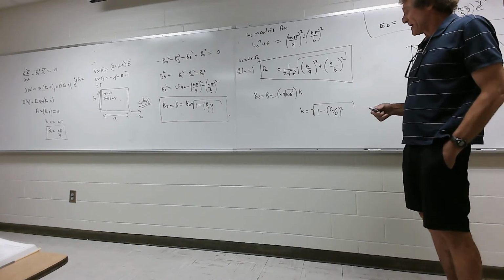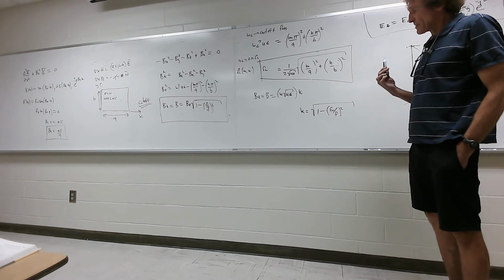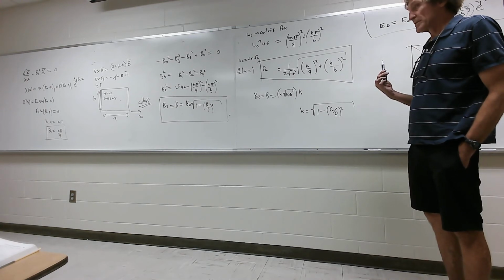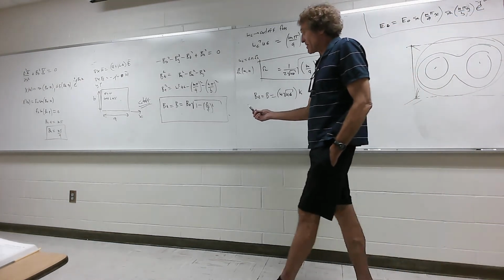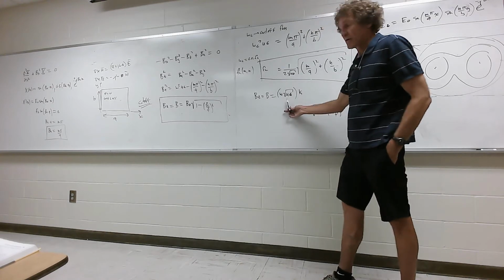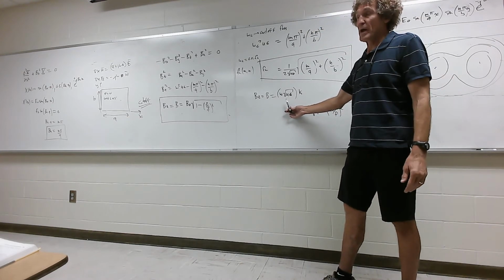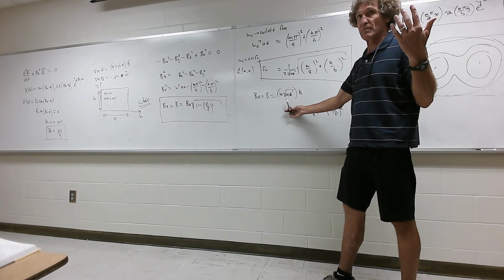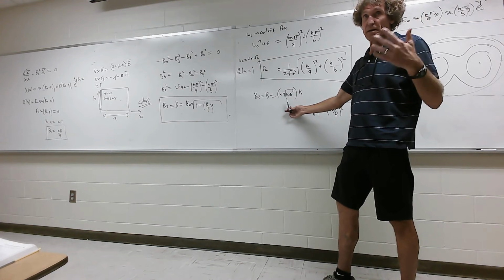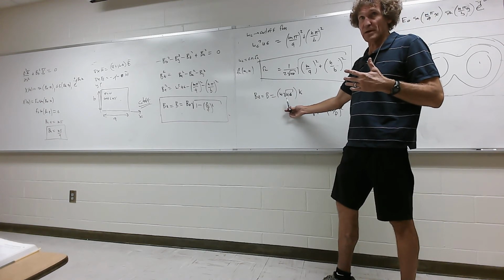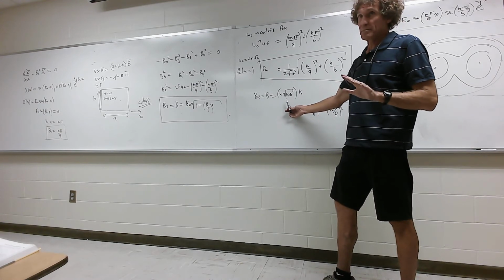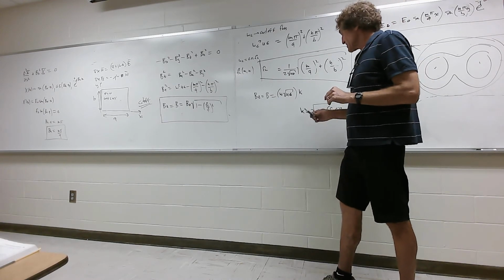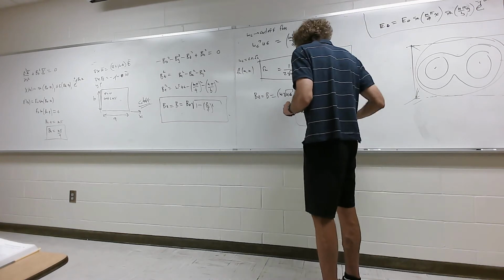But what does this number K really give you? Well, the closer you get to cutoff frequency, the smaller that gets, and eventually it becomes 0 at cutoff. And it really is just a multiplier on beta, on the normal, unguided beta. If the wave was unconstrained in free space, that would be the beta defining the number of radians per meter. Can y'all follow me, class, on that one? Some of it is a little tough to get a handle on right away. It'll take some time. But just try to appreciate this. This value of K is very useful.